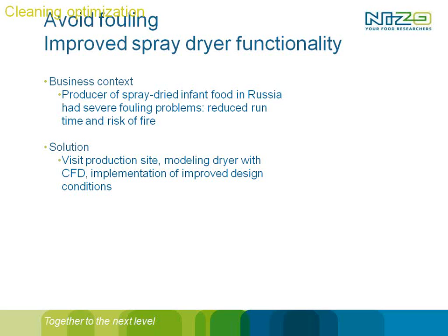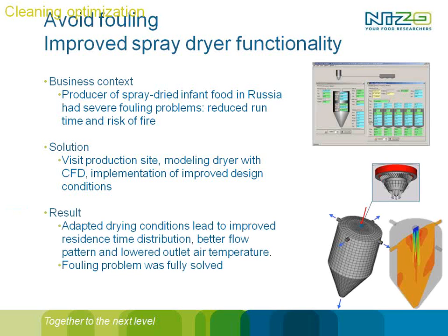What we did, we visited the site, we modeled the spray dryer first within NIZO Premiere, then within CFD, a computational fluid dynamics package, and there you can really model the whole airflow patterns inside the spray dryer. And we proposed improved conditions for the design of the air inlet.